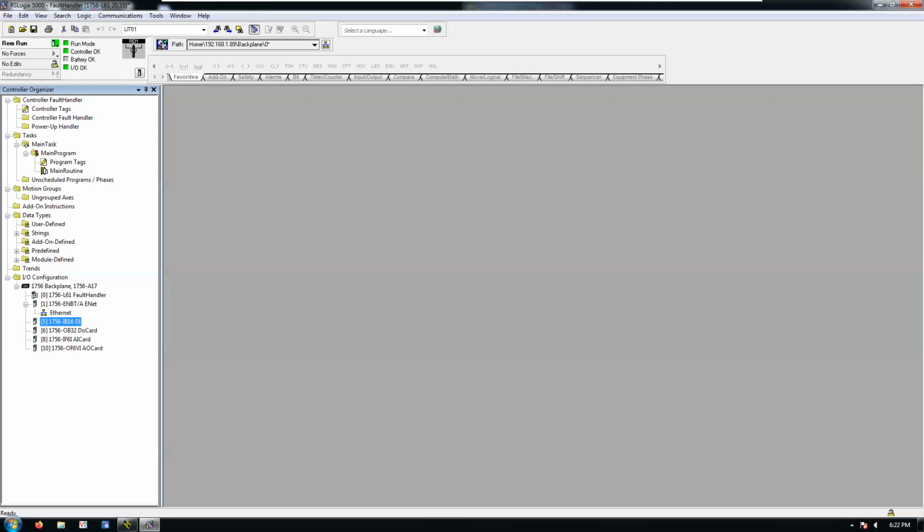So recoverable stuff: negative presets and timers, pointing to an element that doesn't exist in an array. If you remember last week when I had an array and a counter doing some indirect addressing, and I went to write to an element at the end of the array, the processor faulted. That's a recoverable one.